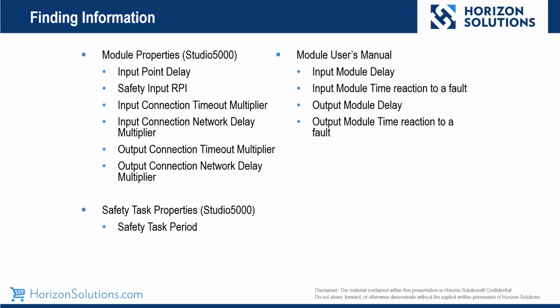We go back to the module user manuals for both the input and output device, and we will find the input module delay and the reaction time default. Module delay is the max time seen between an input and the change of state of that input, or the change of state of the output and the actual output changing state.